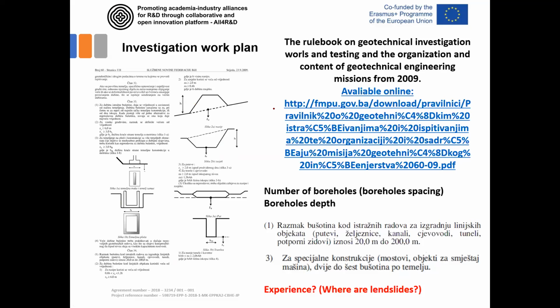So first thing you have to bear in mind when discussing about importance of investigation works in construction and designing the highways in landslide area is what will be the magnitude of investigation works. How many boreholes should we perform? How deep should the borehole be? What kind of field tests should we perform? How many soil samples, rock samples we should collect? These are very important information when asking for some input information regarding the construction of highway in landslide areas.